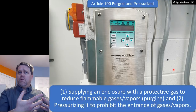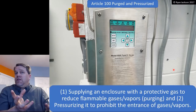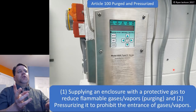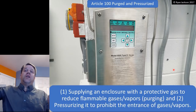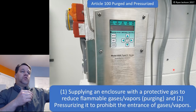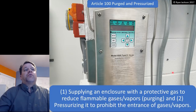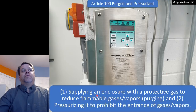That's a very common method. You pump a bunch of nitrogen into an enclosure. Nitrogen is inert. It's a protective gas. Or you could use clean air, outside air, and you purge all of the bad stuff out of the enclosure. That's the purging. And then step two is the pressurizing. You pressurize it. You keep it pressurized to prohibit the entrance of gases or vapors.